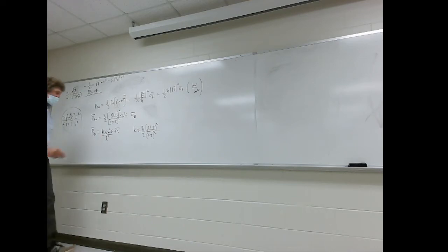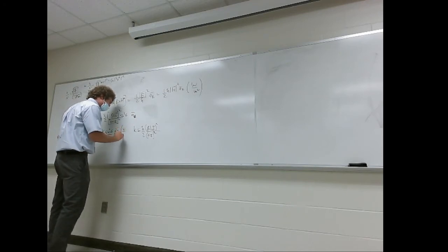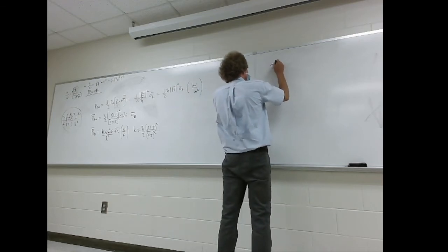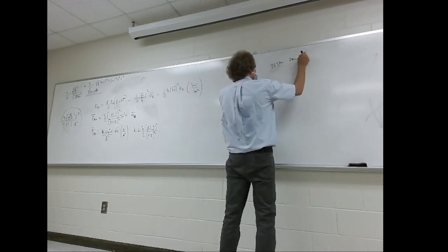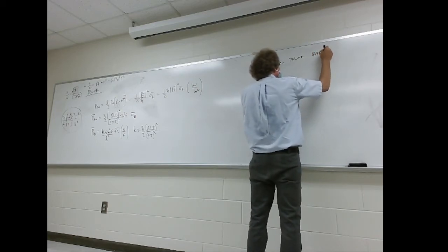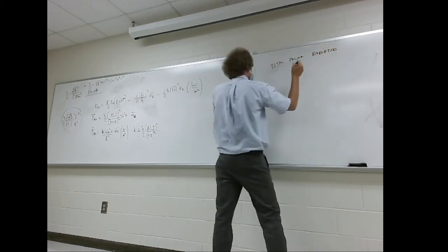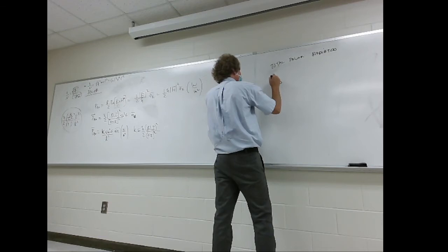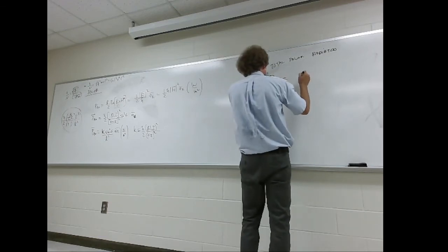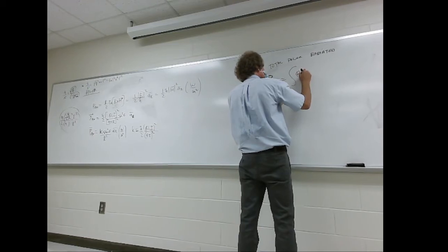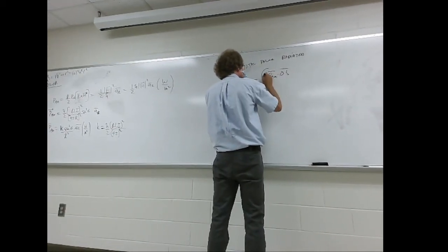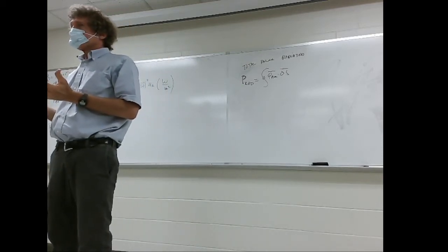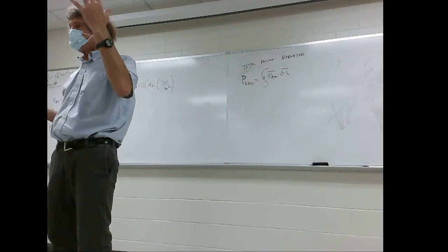All right, so that's the power density here in watts per meter squared. Now when I come over here to find total power radiated, I'll just call this P radiated or P rad. That's what Dr. Wentworth's book has. Well, that would be the integral of the average power density over the surface for a closed surface that encloses the antenna. I'm going to write down mathematically the exact form. Did y'all follow me the concept? You take the average power density.